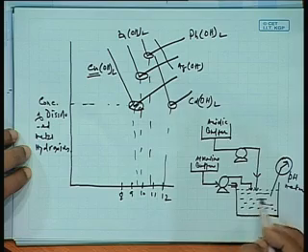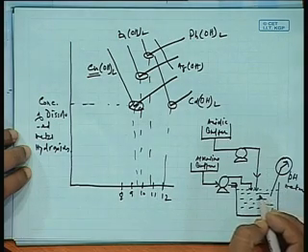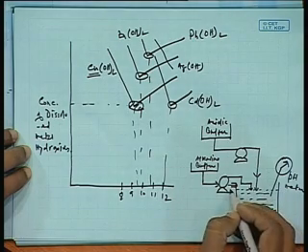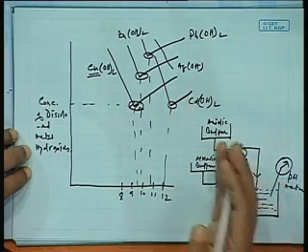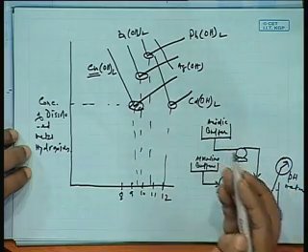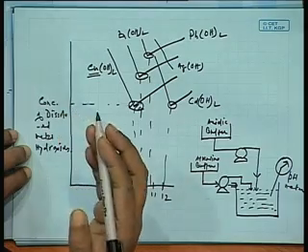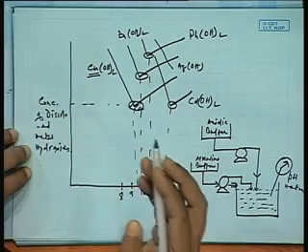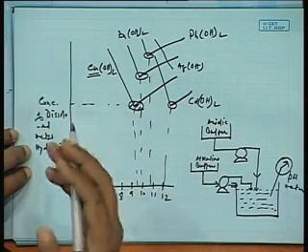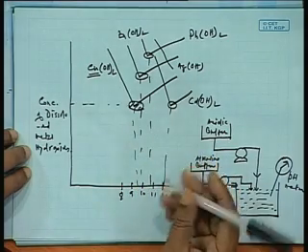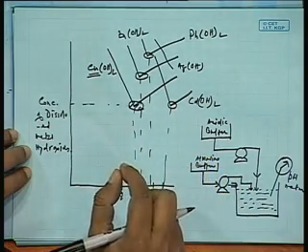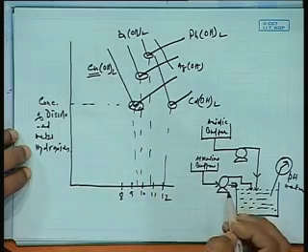So we would like to selectively precipitate different kinds of sulfides and hydroxides. At times when the acidity increases, going from 7, 6, 5, 4, 3, 2 like this, and we want to increase the pH to 8 or 9, we have to use more alkali, so you would use the alkaline buffer.